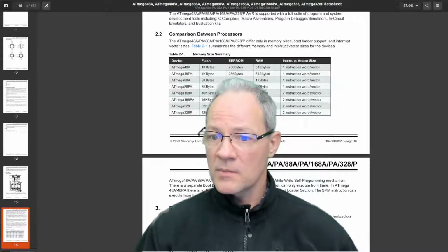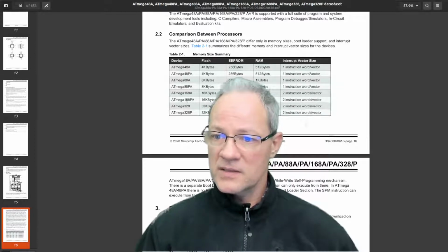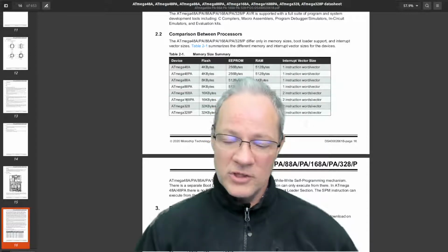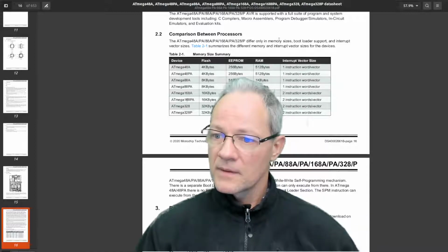The EEPROM is 1 kilobyte. So that's quite a bit of memory actually. But that's the one that we can write and read only 100,000 times. And then there is this RAM, random access memory, that's 2 kilobytes. That's for general purpose variables and things like that, right?